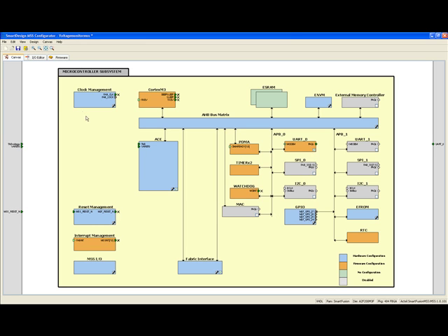Then, on the MSS, highlight ports 24, 25, 26, and 27 on the GPIO block, right-click, and select Promote to Top Level, which really means next level up in the hierarchy. You will assign these ports to a top-level package pin later.